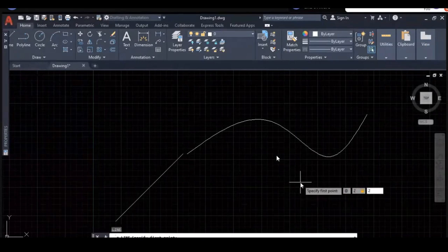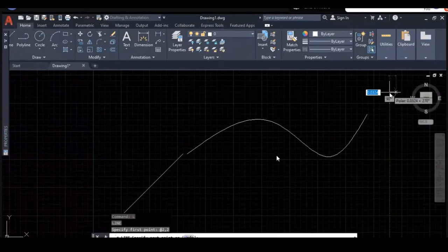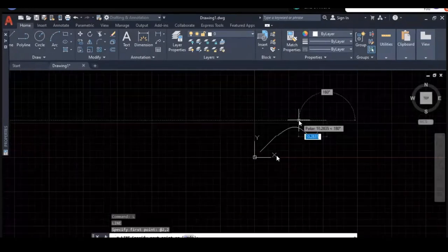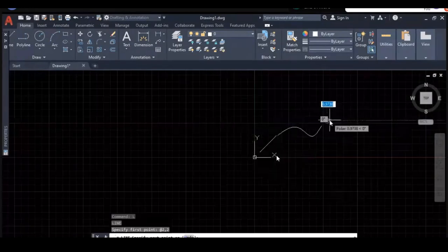See now, before it was a reference, 2, 2 is somewhere near to the UCS icon. When you specify @2,2, what happened? It starts from here. What's the difference? We typed the same values, 2, 2. There is no change in magnitude. Then how does it come to know the values differ from previous point to this point? The coordinate system which we specified plays a crucial role here.